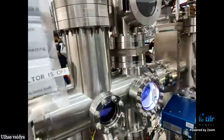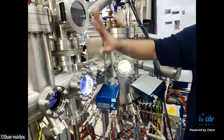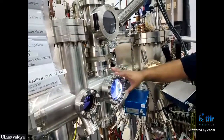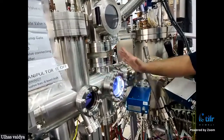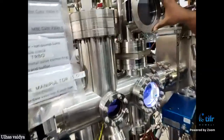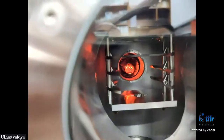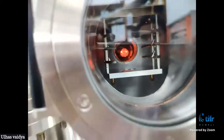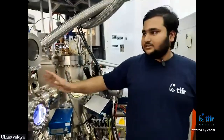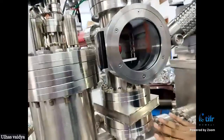So we have divided our chamber into three main parts. This part is the main chamber, and this part is called the buffer chamber, which is both a preparation chamber and a storage chamber. I will explain what we do here. First of all, this is called the first entry load or FEL chamber. This is the chamber which we open to atmosphere directly. No other chambers see the atmosphere at all. When we open it to atmosphere, we close this gate valve so that no high pressure goes into the buffer.